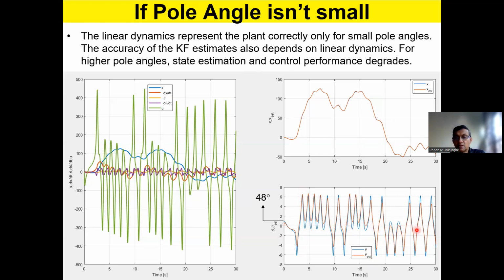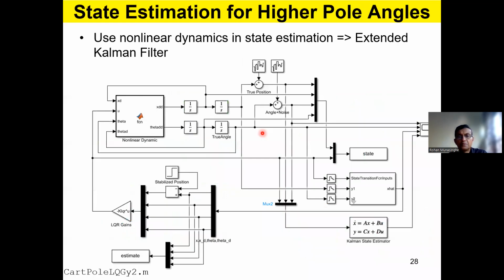There are errors at times. So I'm showing you the limits of the Kalman filter, right? The performance is not that good with a single sensor, but with two sensors, we have some better performance. But again, when you have bigger errors in initial conditions, big offsets, that won't help. So we need to improve the performance of the filter.